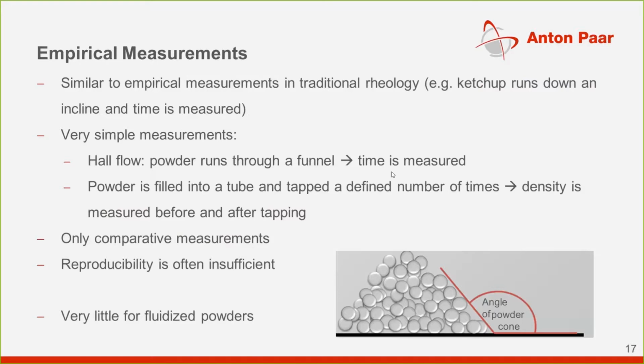Another method is, for example, to tap the powder and look at the tapped density, so look at the density before and after tapping and put that into relation, which will also give some information on flowability. There is not so much that exists for fluidization experiments from these rather empirical methods. Anyway, what we can still say is that these measurements are usually only comparative, so not absolute measurements, and the reproducibility often depends on the operator, or sometimes they're just not very reproducible.